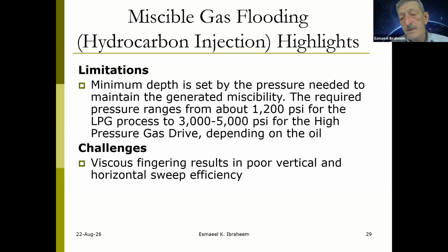The limitations of the hydrocarbon injection: the minimum depth is set by the pressure needed to maintain the generated miscibility. The required pressure ranges from about 1200 psi for the LPG process to 3000 to 5000 psi for the high pressure gas drive, depending on the oil.